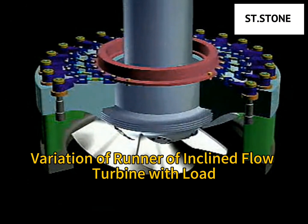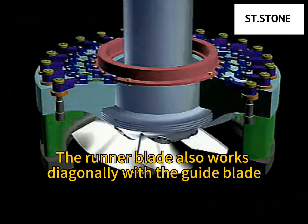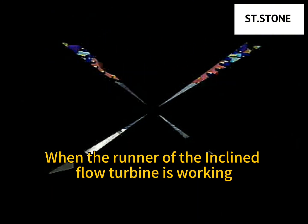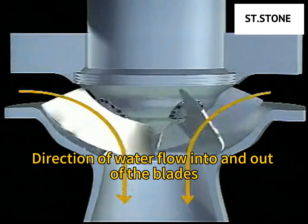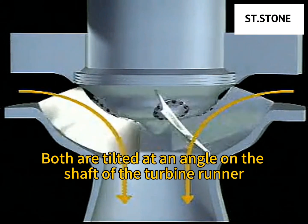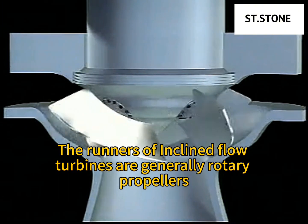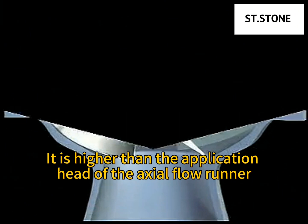The runner blade varies with load, also working diagonally with the guide blade. Therefore, its structure is similar to the axial flow propeller runner. When the runner of the inclined flow turbine is working, the directions of water flowing into and out of the blades are both tilted at an angle to the shaft of the turbine runner. Therefore, it is called an inclined flow turbine runner. The runners of inclined flow turbines are generally rotary propellers. It is higher than the application head of the axial flow runner.